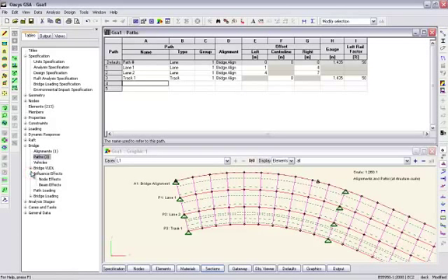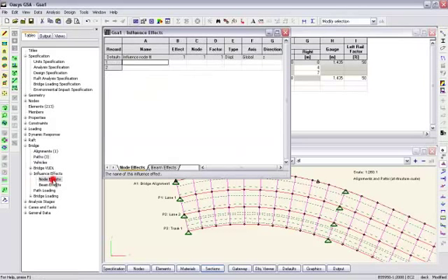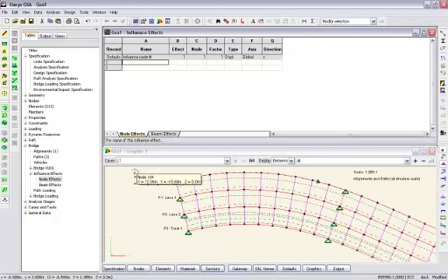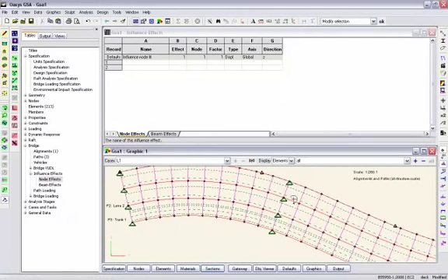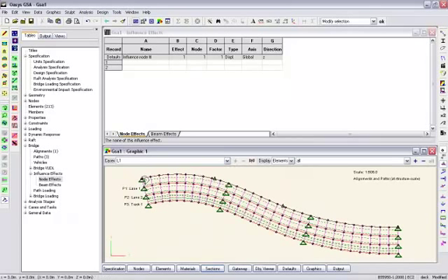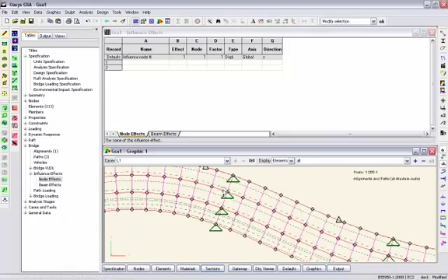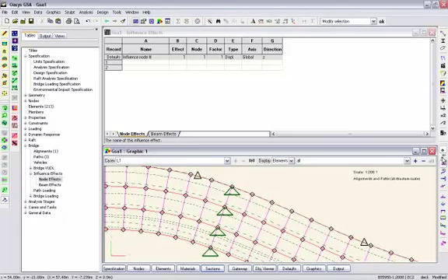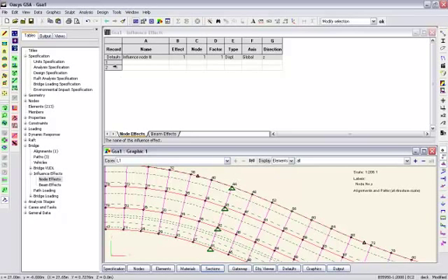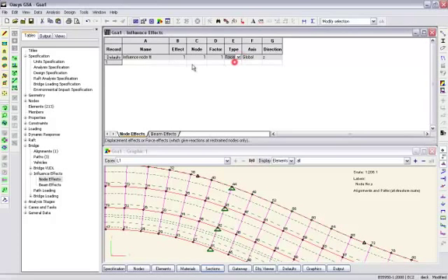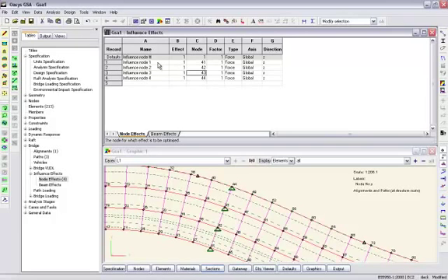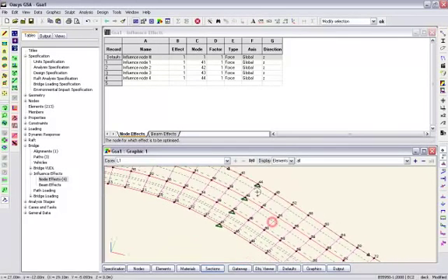We now also need to create the nodes, the influence points which we're interested in. So I'll do the nodes first of all. For this bridge, for the vertical reactions we'd actually need 4 sets, but I'm just going to take this line here for simplicity. The others are the same, and so these are going to be nodes 41 to 44. And so I set my defaults to false. 41, take the defaults. 42, 43, 44. And let's just check on that.